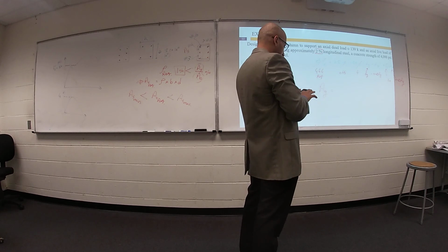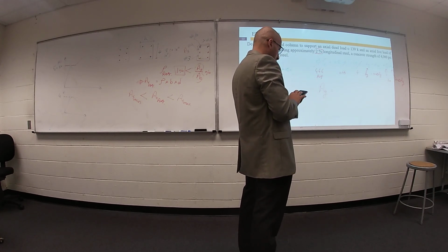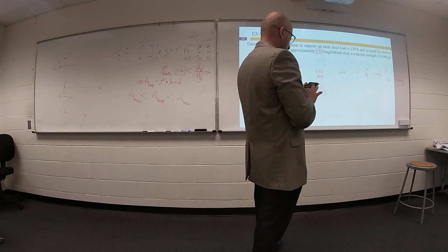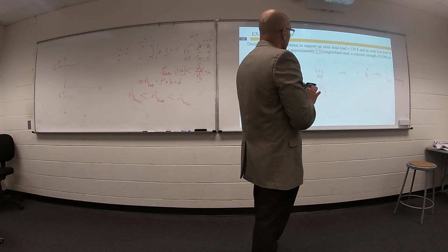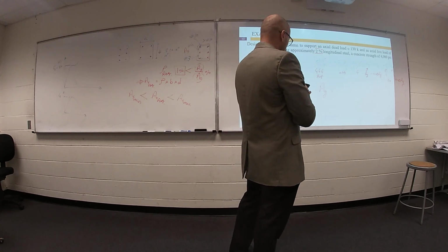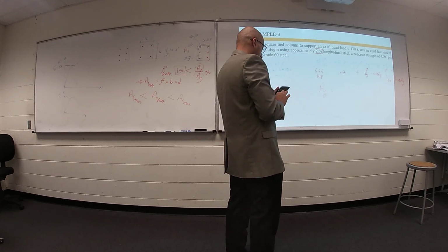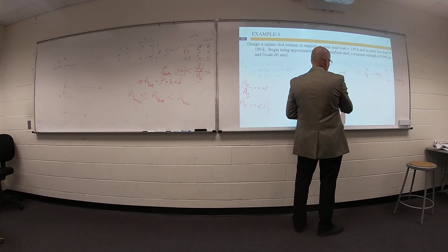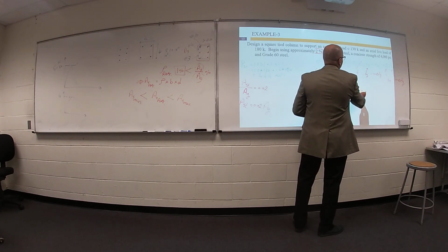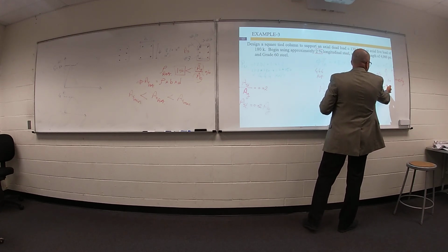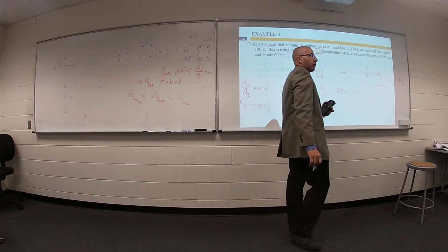What's the value of area gross? 444 divided by (0.65 times 0.8 times (0.85 times 4 times (1 minus 0.02) plus 60 times 0.02)) gives 188.4 square inches. This is the area of your column cross section.